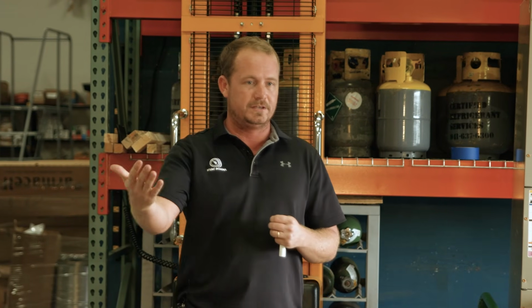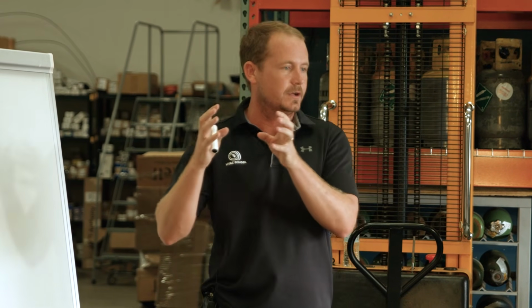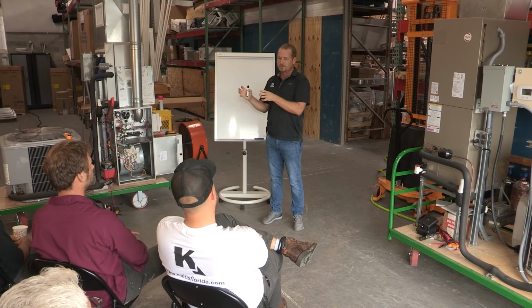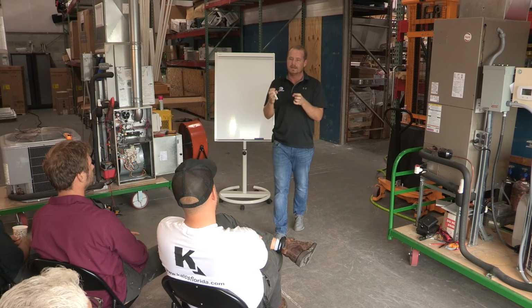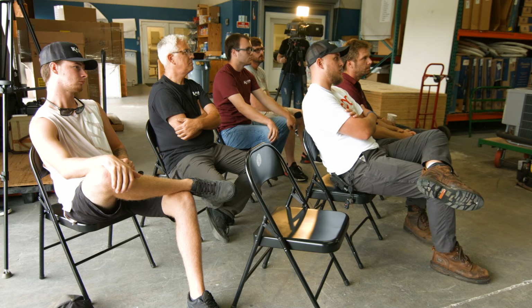We could have a two-stage system. They could have Y1 and Y2. Let's use that as an example quickly. Y1 and Y2. What do you need in order for a two-stage residential piece of equipment to run at full capacity, in terms of your terminal designations? What do you need to energize? Y1 and Y2. Y1 and Y2, right?